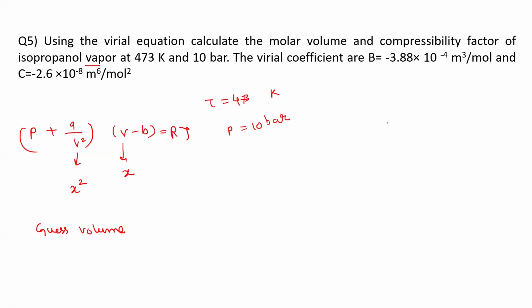So out of the three roots, whatever you get, the three roots can be, one of them is real and two others are complex. Or all three are real. And in which one is very less, showing the liquid, and the one is large, which is vapor volume.